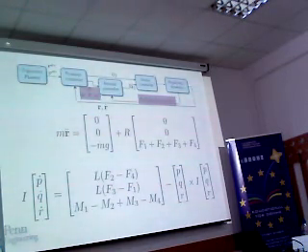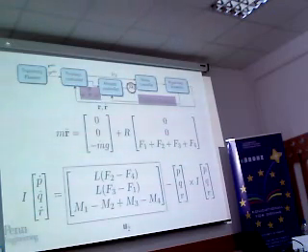And from that, we want to calculate the input U sub 2. U sub 2 is a function of the full thrust and the moments that we get from the motor speeds. So here you have U2 is a vector composed of three components. This one is the moment with respect to roll, pitch, and yaw.